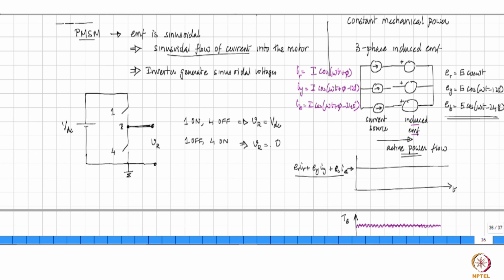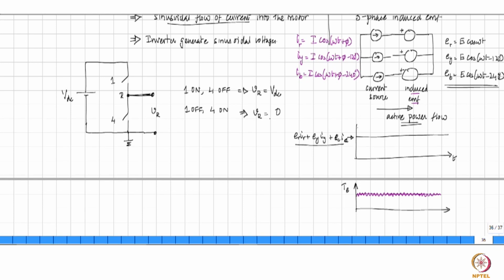So you can never get a negative voltage from this. It's not feasible. You cannot go to a voltage lower than 0 because the structure doesn't allow it. But if you want to generate a sinusoidal voltage, you have to have negative voltage. Voltage has to go negative. So what you do is, you don't generate a sinusoidal voltage with a 0 mean, you generate a sinusoidal voltage such that it is VDC plus some A cos omega t.